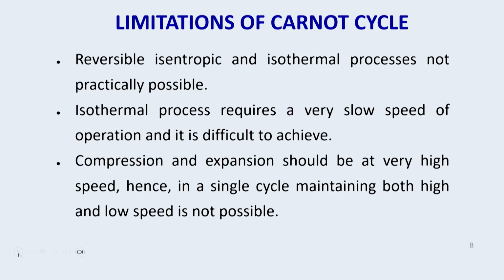Let us see the limitations of the Carnot cycle. What are the limitations? In the Carnot cycle, all the processes are reversible: two isothermal and two isentropic processes. Achieving these processes in practice is very, very challenging. It is impossible, because any thermodynamic process in a real application is irreversible, in the sense that it cannot be reversed perfectly.